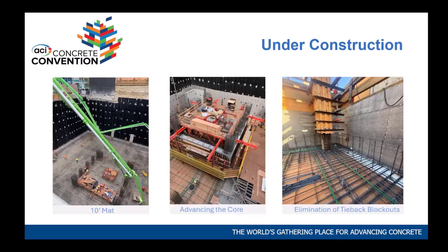Now, the underground, the below-grade construction was really interesting. First of all, we started with a mat. We had a lot of cool concrete specifications for different concrete mixes for the building, but the mat is basically about 10 feet thick. Around the elevator pit it is about 15, but most of it is about 10 foot thick. And they did a single pour for the entire mat, about 5,000 yards. They start at night, they finish in the morning, about a 12 to 14-hour pour.